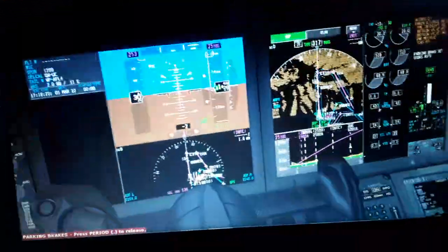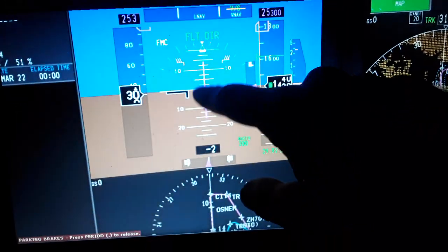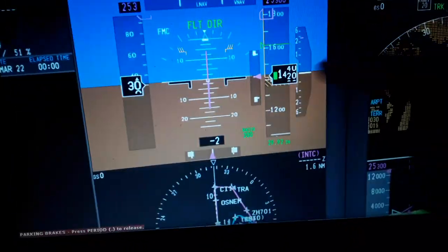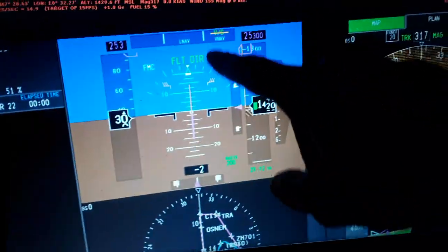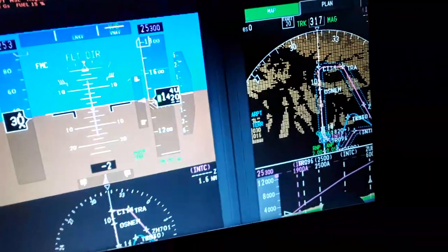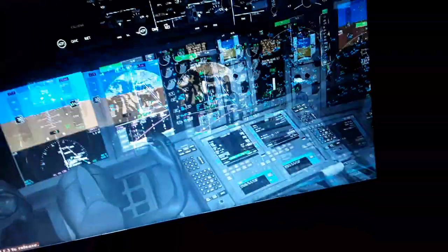So you can see here now we have engaged the airspeed from the autopilot flight director system panel. Target airspeed, target altitude, pitch attitude in flight, vertical rate of climb or descent of the aircraft, and the barometric altitude where we are located right now, flight mode annunciator, radio altitude of the ground level. So this is all the air data, and we have a couple more things to do.